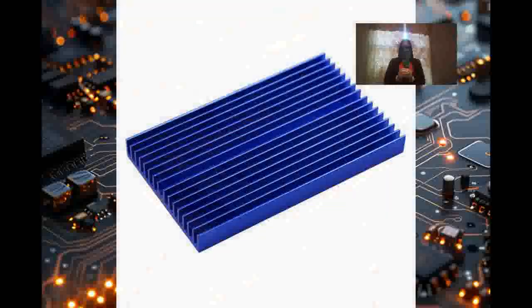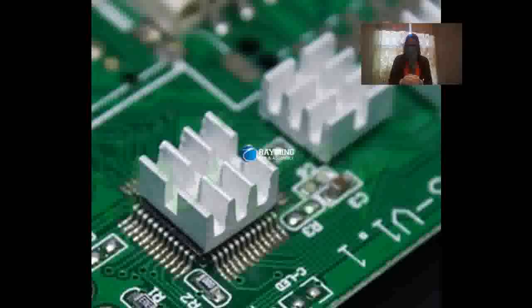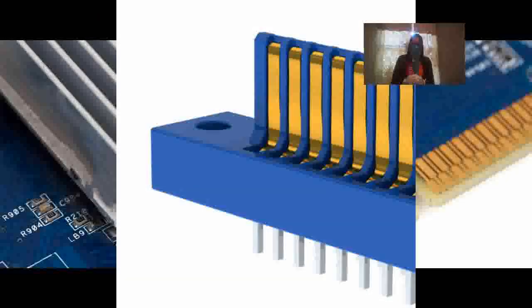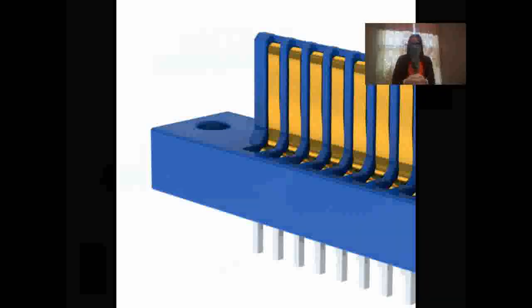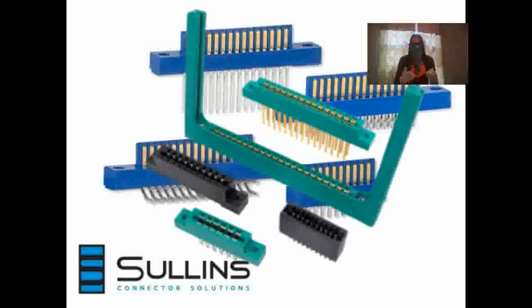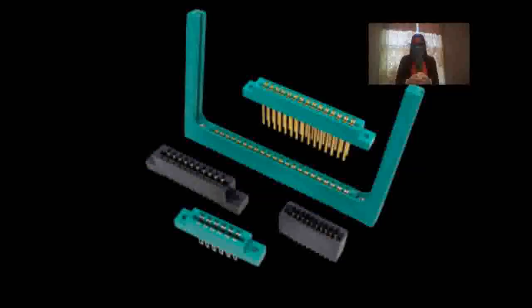A heat sink area is a wide copper surface that is used for a common connection point for many devices, as well as to dissipate the heat generated by the electronic devices. Edge connectors provide the electrical point for attachment to other electrical equipment. The conductor paths can be less than 0.001 inch in thickness. These strips can be one side or both sides, depending on the design of the board. The currents used on most boards are very low and usually do not require heavy wiring.